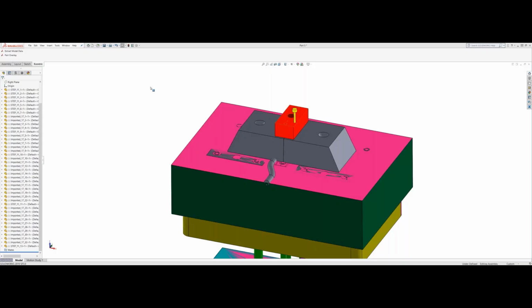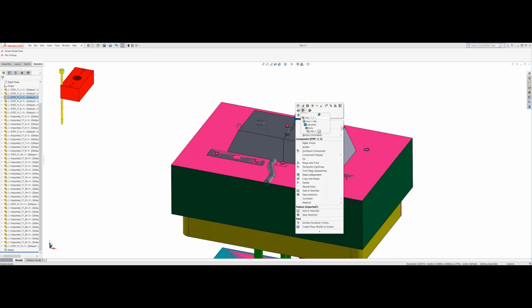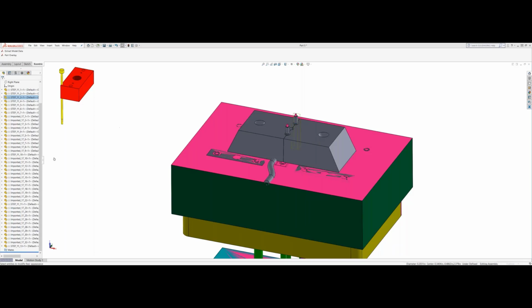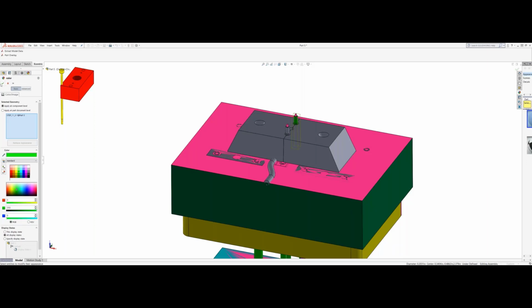John, you said this is an automated tool? Yes, it was. Then we have a question: is the material of the manual tool different than an automated version? Some components may be made out of steel just because of the wear. In particular, slide faces and things that bear the brunt of the shutoff we may make out of P20. It really depends on the situation.